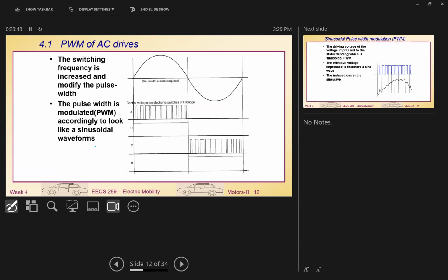If you look in more detail, you can see that this still carries a sine wave pattern. So that means we're not actually giving the motor a sinusoidal continuous waveform, but giving it a chopped PWM waveform. We use this method to make the motor feel like it is being excited by a sine wave. So that's how it is actually happening.